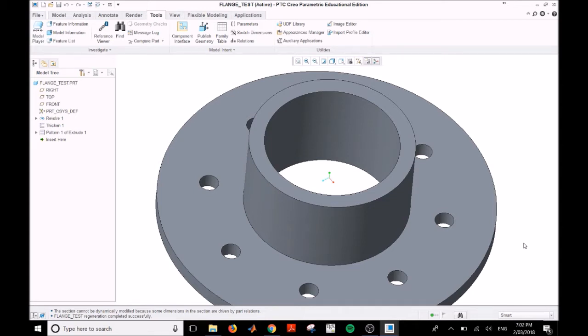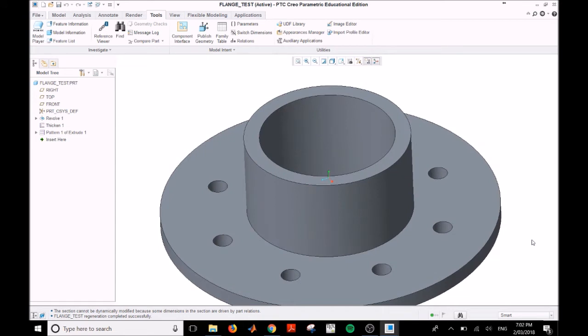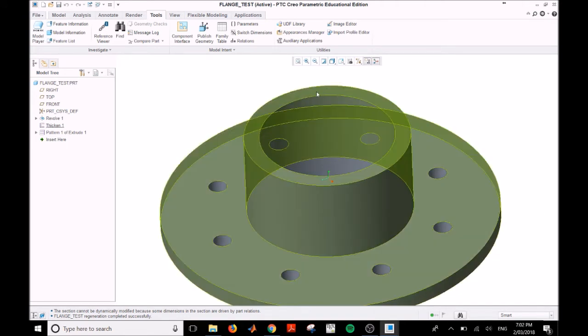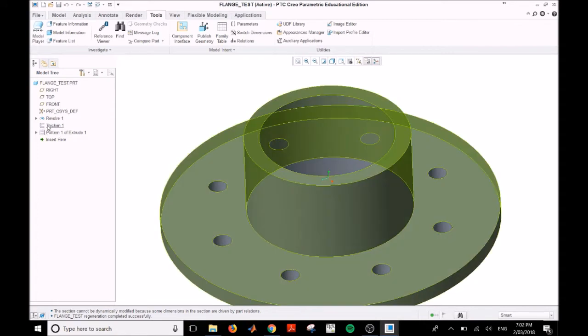As you're aware by now, Creo does this implicitly with simple shapes like squares or circles or some shafts. But the real power for the user is the ability to define these relationships based on the model. So the general workflow is to create a model that roughly represents your finished product.